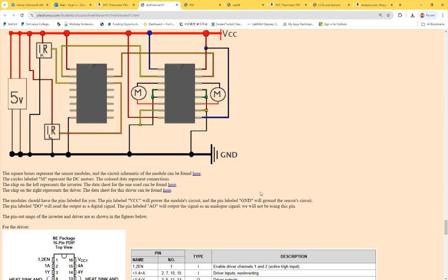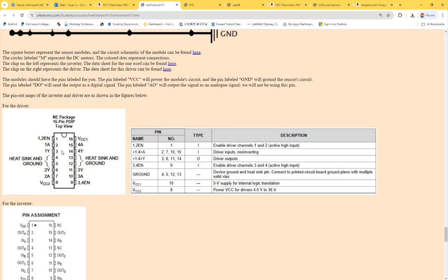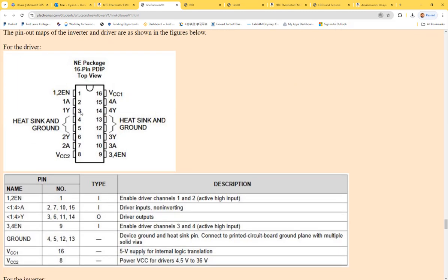Okay. So here's a tutorial on how to use that chip. Super simple. Promise you, even high school students are able to do it. The connections are super simple. You have a DC motor, you connect it to these two pins and enable it. This is logic on and off, so you can use PWM to control it. So you can control the speed of the motor.